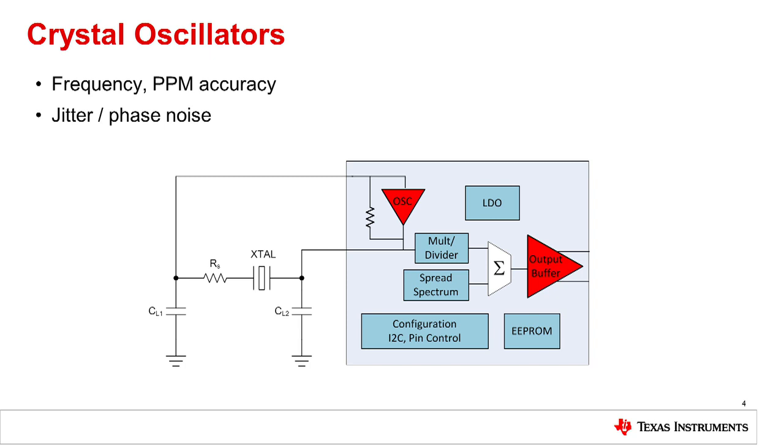A simplified circuit for crystal input is shown in the figure. A crystal is connected across an inverter input and output, where R sub S is a series resistor used to reduce the drive level if needed. The active circuit inside the chip generates a positive feedback loop, otherwise known as negative resistance, providing a stimulus in order for the crystal to start and maintain oscillation.